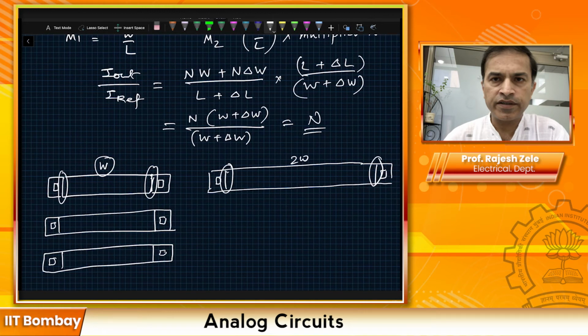Instead of just scaling the area of the capacitor, if you want really exact capacitive scaling, let's say you want a ratio of 10 between C2 and C1, then you don't just increase the area of C2 by 10. What you do is you make one capacitor C1, and then you stamp that capacitor 10 times to get your 10 times C1. So this particular philosophy, you use it for every component that you would be laying out on the chip. And these are very specific to chips, because you're drawing all these devices on the chip and you would like them to match very well.